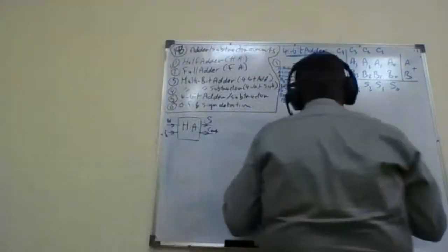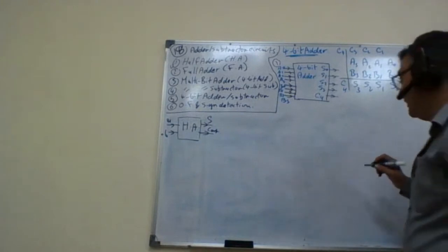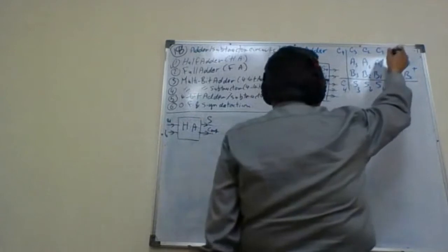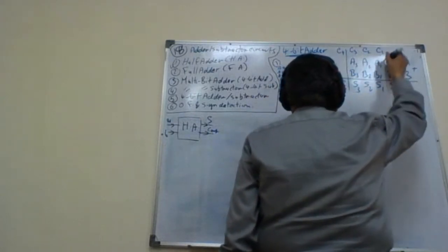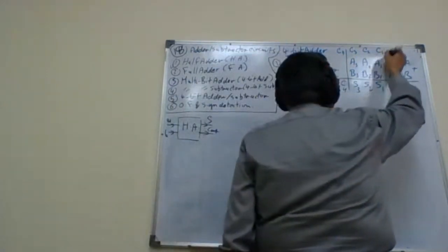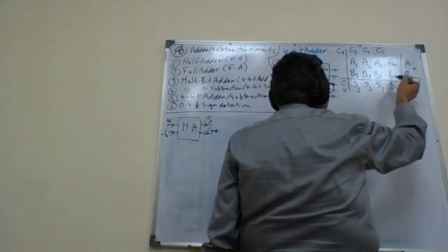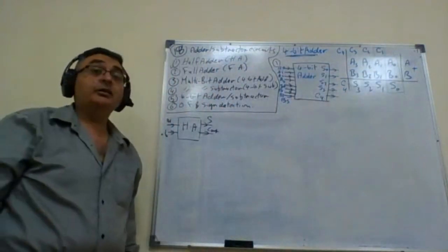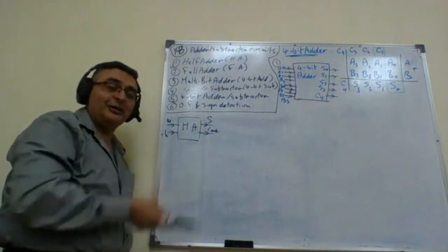If you review the technique of addition that we performed in chapter 1, you will find that we actually add the first two bits together, and from adding A0 to B0, we produce S0 and C1. Can we build this circuit? The answer is yes. This circuit is called half adder. Already built it.